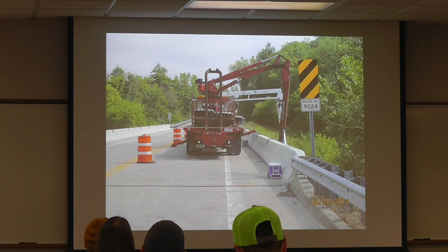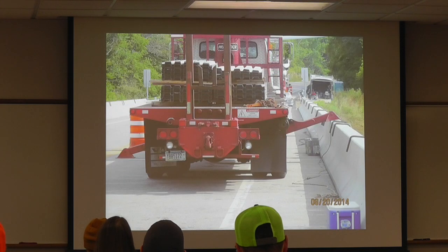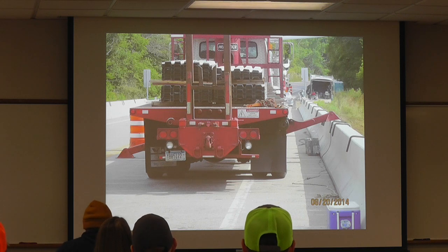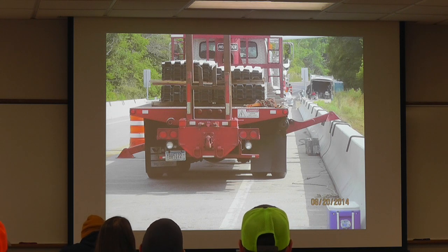Anybody see anything goofy here? I hear some chuckling. I don't think barriers make a good pad for an outrigger. It's not often you'll see that kind of thing, but when you do, no, just no. Make sure the contractor fixes that.